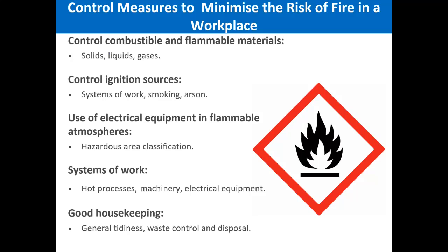So you need to basically make sure that you classify the various hazardous zones and use equipment according to those classifications. Basically, there are zone 0, zone 1, zone 2. Every country has their own classification. You don't need to remember this, but zone 0, zone 1, zone 2 are various hazardous zones which are defined in terms of flammability. A zone 0 basically is an area or a zone where there is always a risk of fire.